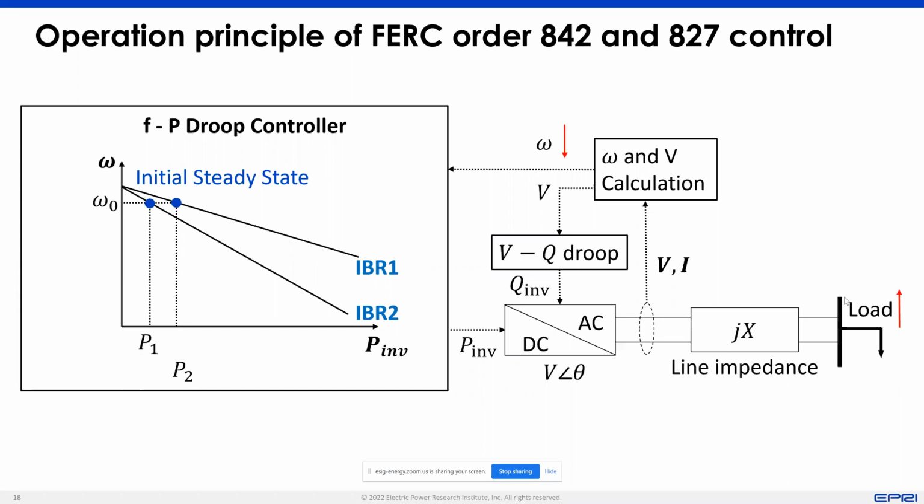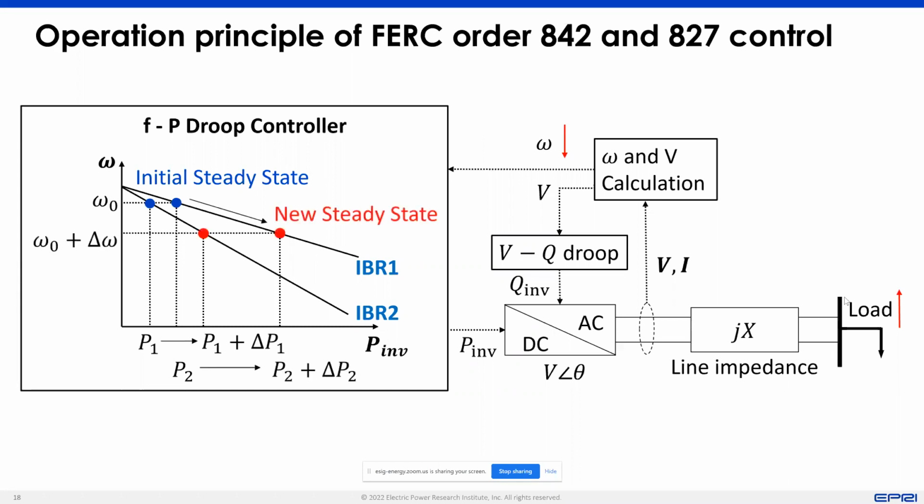So in this particular scenario, this frequency drop will be caused by the PLL. And because of this frequency drop, it then knows to increase its active power generation to pick up the load. And at the same time, if you have multiple machines or multiple inverters in this scenario, in the system, they will again share the load based on these two droop curves.